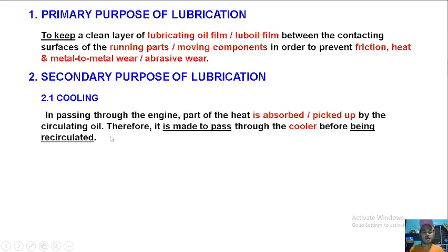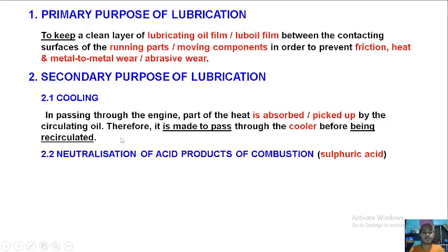In passing through the engine part, the heat is absorbed or picked up by the circulating oil. Therefore, it is made to pass through the cooler before being recirculated. Next is neutralization of acid products of combustion, especially sulfuric acid.